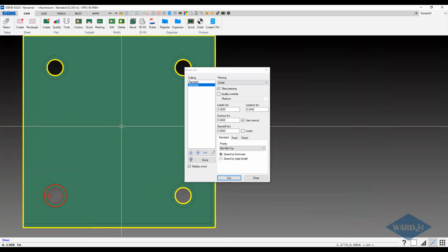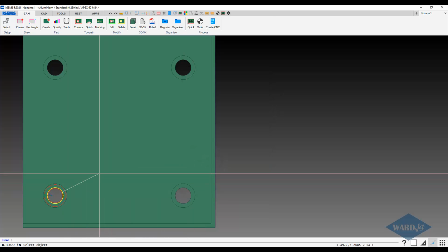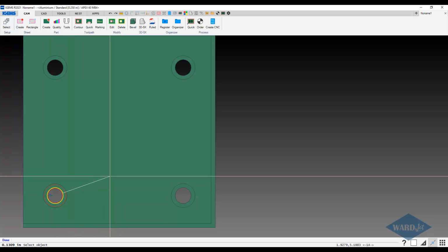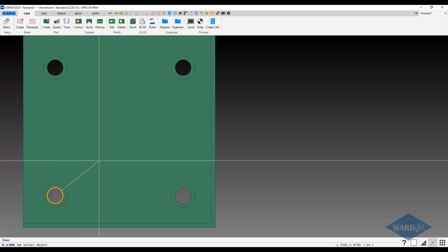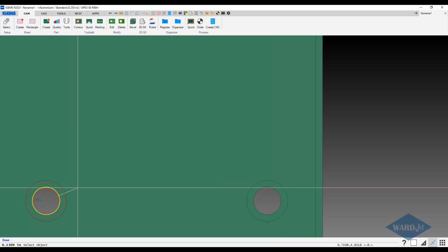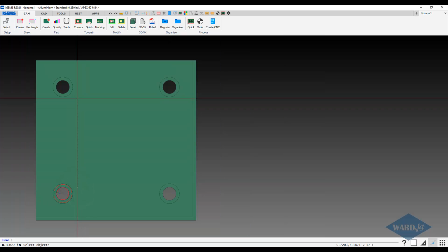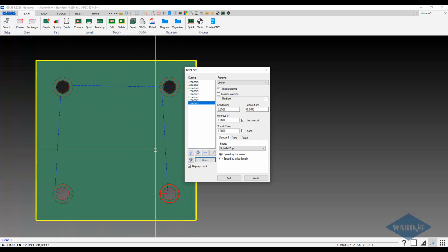So we could do the same thing for the other 3 holes. There is also the clone tool here, so I can click on clone, and it connects the little connector line here showing the cut that I can clone. Since there's basically only one contour here that has cuts that I can clone, that's the only one this will connect to. So I left click to indicate that that's what I want to clone, and then I can click on the objects that I want to clone this to. So I just left click on each of these and then hit enter, and that gets copied around there.